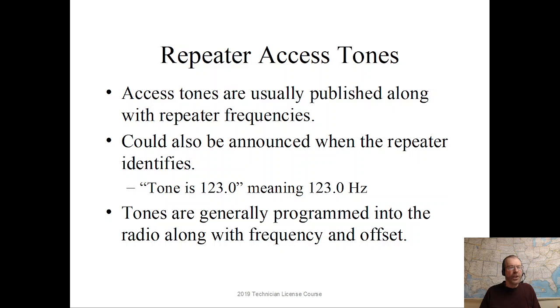And their tones are generally programmed into the radio along with the frequency and the offset. Tones are very common right now. There are very few repeaters without some kind of tones or digital code squelch.